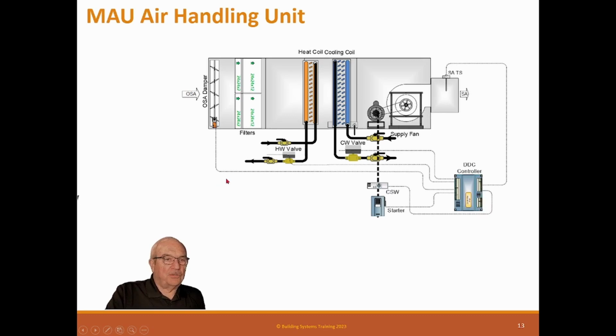So of course, they have a control system. It's pretty simple. Almost always constant volume. There can be VAV, but normally it's not required unless you have an active building pressure sensor. So normally it has a constant volume fan, it has a cooling coil and a heating coil, and normally in this configuration, not set up for dehumidification. The reason is because they're just tempering air that's going to be wasted, right? It's going to be exhausted. So basically we just want temperature. We don't want anything fancy. We have filters, and we have an isolation damper on the outside air.